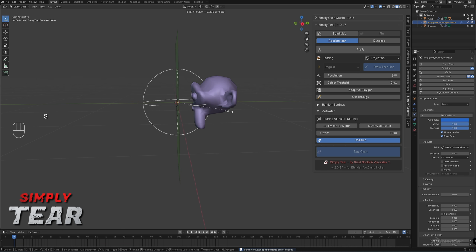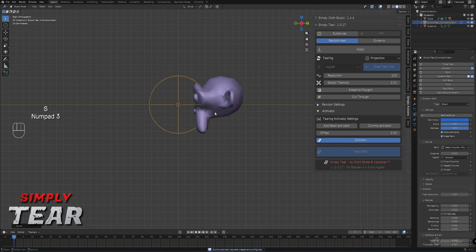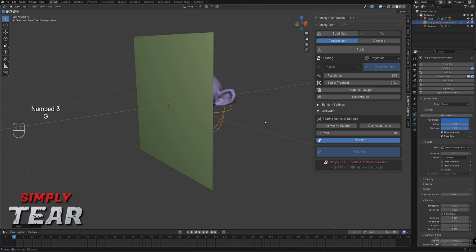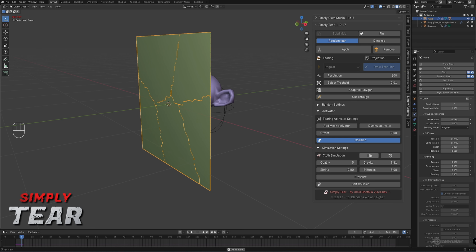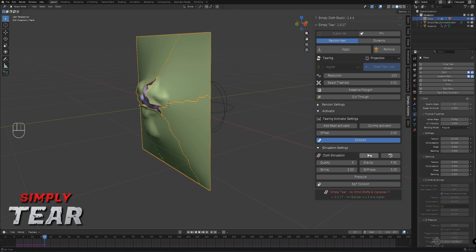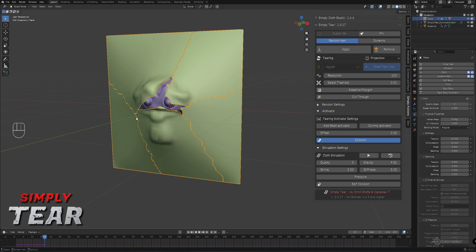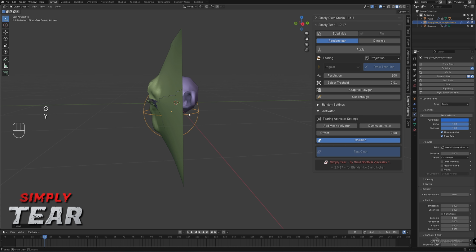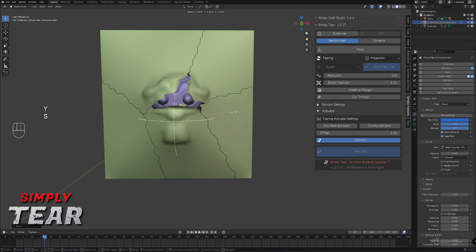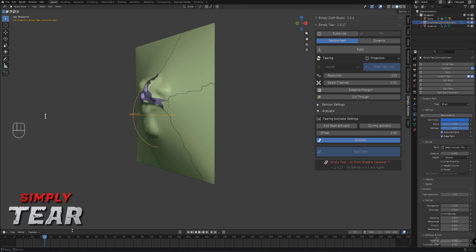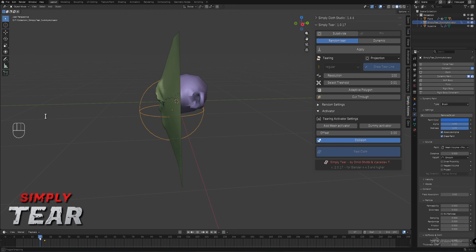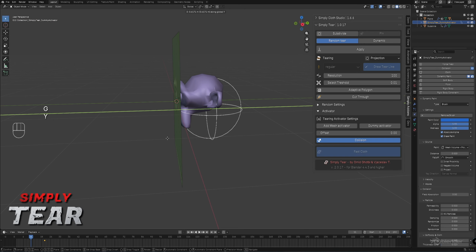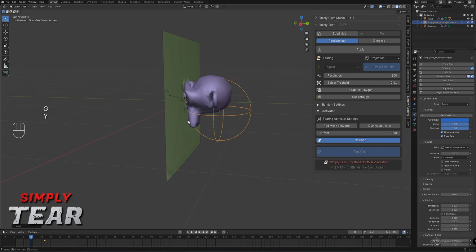We can have as many as we want. Now checking the simulation, we see when this should tear, like around frame 20. So we use this activator in this scale and hit I for insert keyframe, and here it should not affect it at the moment.